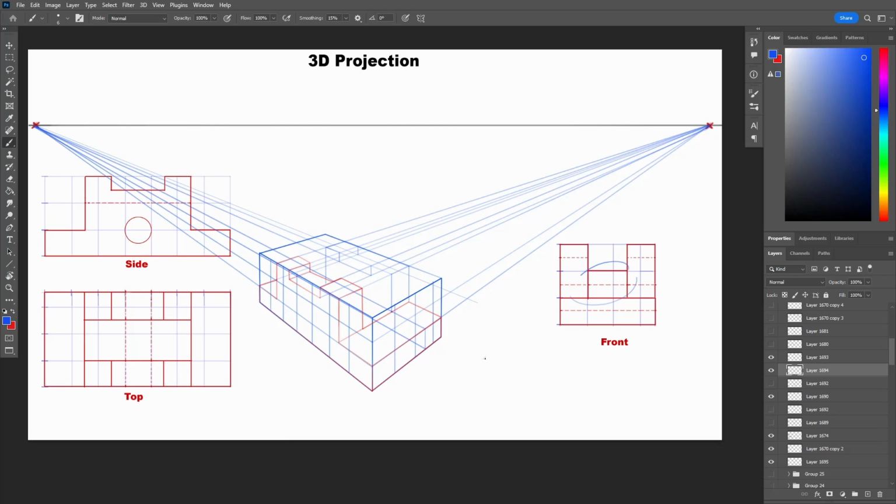Next, I draw the bridge in between, which is 1 unit up and 1.5 unit in width, as we see it in the front view. And we can see from the top view that the bridge is 4 unit wide, stopping at the lower platform.